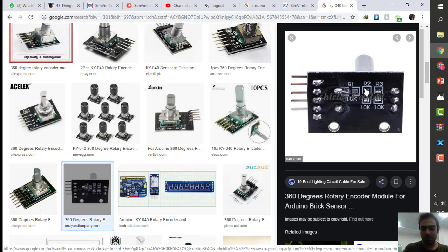It's a very simple process using a soldering iron. You remove these 2 resistors, and you are not going to use these pins. You are going to use the raw exit of your encoder. I'm going to show you how I did it in the video right now.